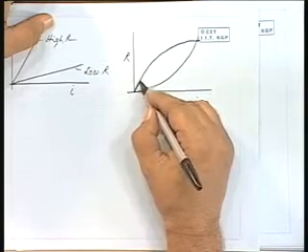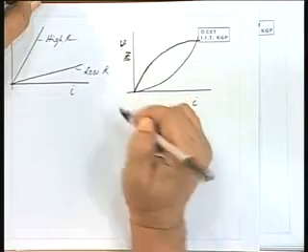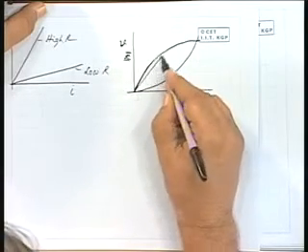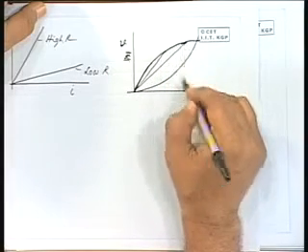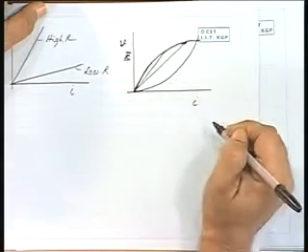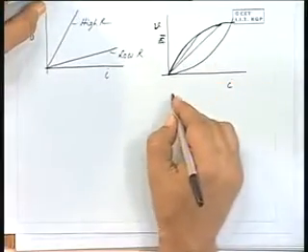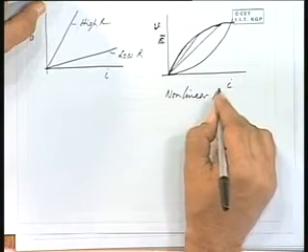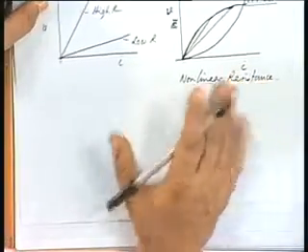Here this is the voltage, say. The slope represents the resistance value, so resistance keeps on falling in this case. Voltage by current ratio does not remain same. In the other case, it may increase. So this is the example of a nonlinear resistor. Best example is incandescent lamp.